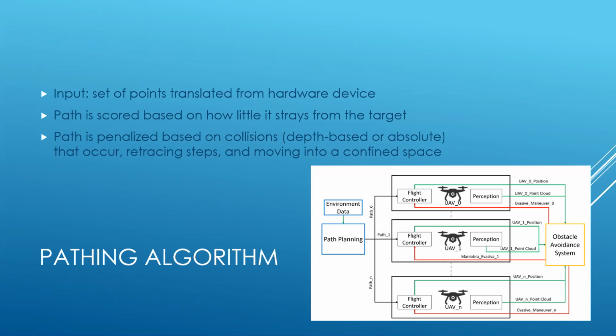After the path has been selected, there will be frequent communications between an obstacle avoidance algorithm and the flight controller, taking in new perception data each cycle. The process ensures that environmental conditions along the path have not changed to the extent that it becomes unusable. If this is found to be the case, the path will be canceled and a new set will be calculated.